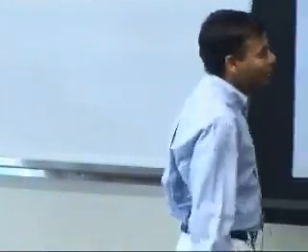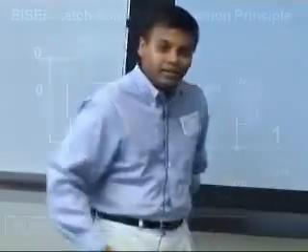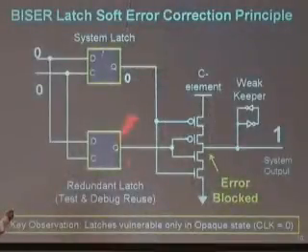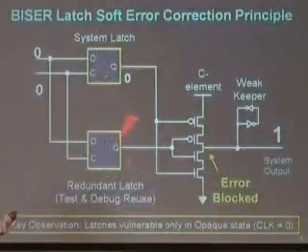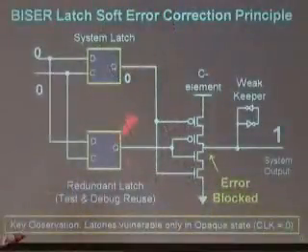And yeah, go ahead. What about an error in the C element? Right. That's a very good question. So let's try to understand what happens if there is an error in the C element. Well, under a single error assumption, these two latches are going to drive the C element very strongly. So the maximum you will see is a glitch at the output of the C element. And that glitch will go away in the subsequent stages of the combinational logic. But very good question. So please ask these questions. Otherwise, it's very hard to talk about everything. Okay, but good. I'm making people think.